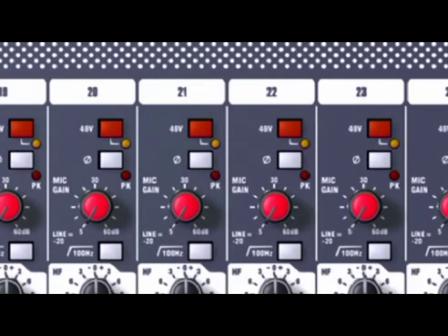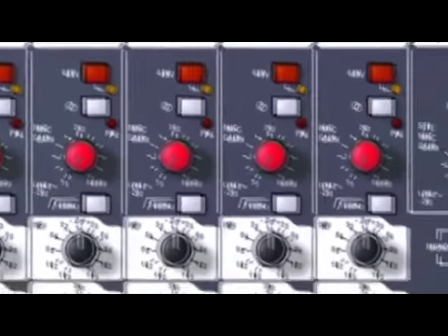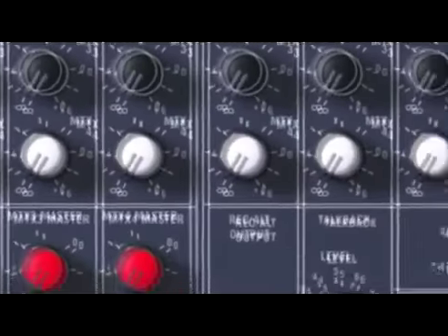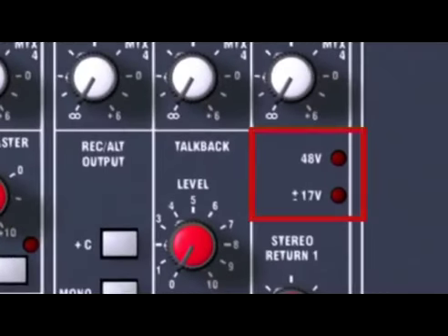Condenser microphones need power to make them work. Some work with batteries, but most of them can also use the mixer's phantom power. Just switch on phantom power for any microphone that needs it, but make sure you don't activate a global phantom power switch if you've got unbalanced sources connected to a mic input. You could cause serious damage if you do this accidentally.